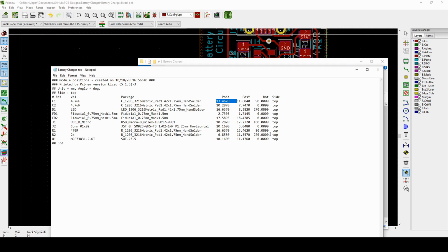Later on, we'll also make a video on how to make sure that the component you create actually has its pick-up point from the nozzles in the center, because your footprint says where the nozzle is going to pick up your component for the pick and place machine.